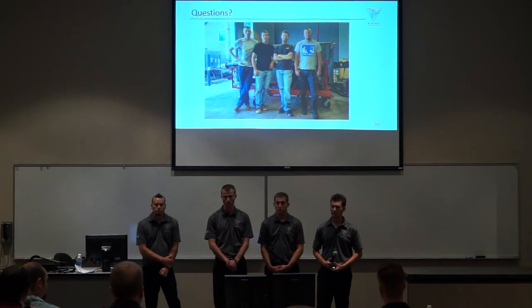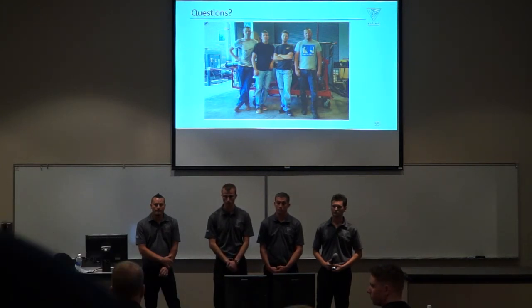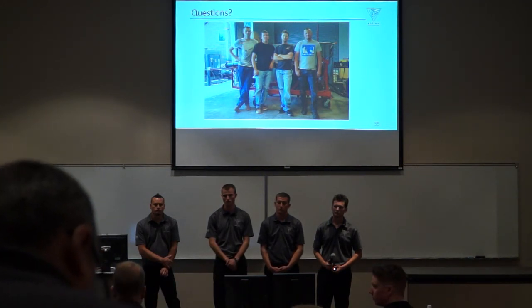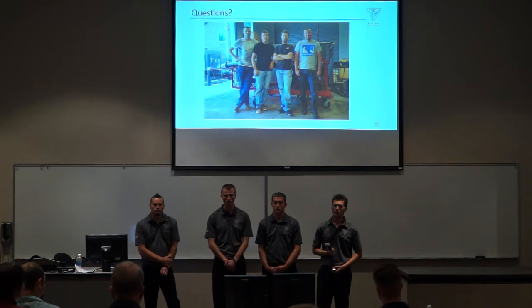Okay, so a little bit into the project, when you were realizing that you weren't getting the total pressure that you were hoping to get, did you do a total pressure loss analysis? You have a dump diffuser in there. Do you have some idea of the flame holder and the dump diffuser and the length of your afterburner, any idea how much total pressure loss that was going to eat up by the time we got to the nozzle throat?